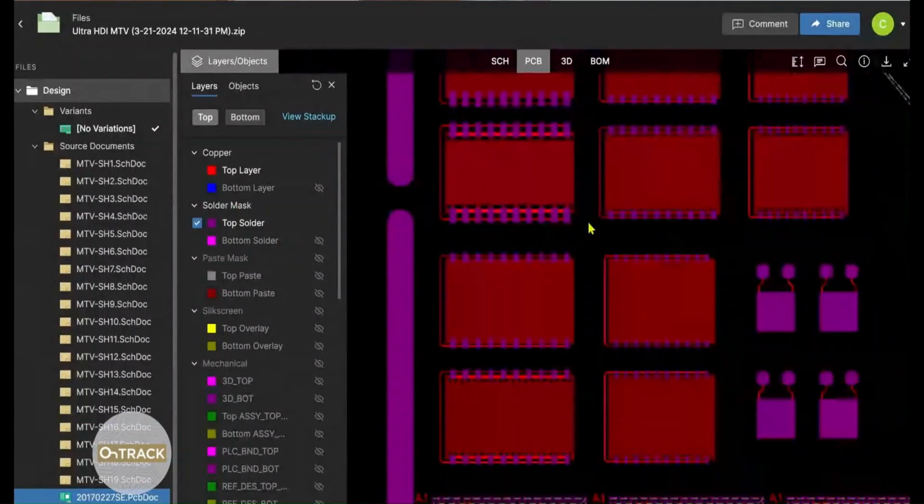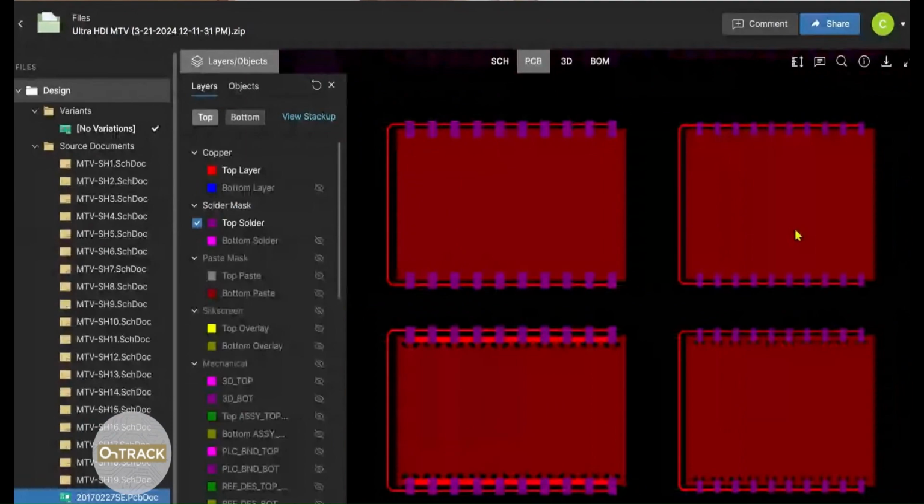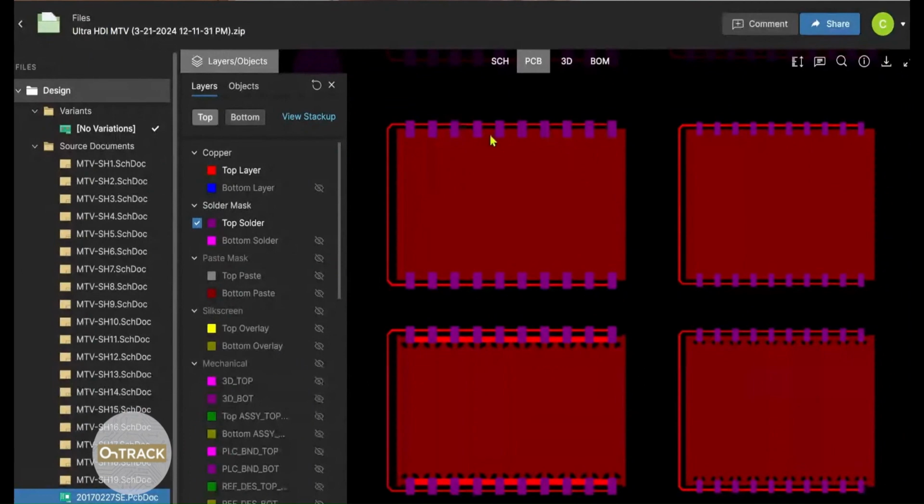But now we've got this new phenomenon that we just designed in down here, and we set it up similar to the Tombstone Alley. I've talked to 3 different assemblers in the last month who are dealing with bottom-terminated Zener diodes. These are 0201 or 0805 or 01005 packages, and they have very small bottom terminations, and they're very light. So what happens is, again, the side that melts first, the solder pulls it. It doesn't pull it up because it's bottom terminated. It pulls it laterally, and you will see all of these skew by the same degree in the same direction when they have the uneven thermals.